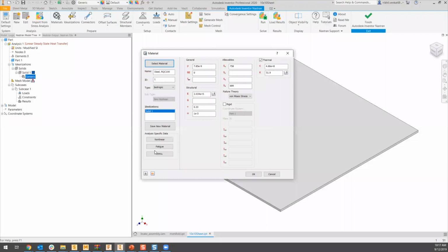Now, by the way, one of the things that I didn't mention previously is this is also how you would analyze heat transfer at areas that are going to be welded, right? So you're not actually going to be able to analyze the weld beads themselves, but you will be able to analyze, excuse me, the temperature profiles of the two materials being welded. So if you want to look at what that temperature profile looks like, you would need to do a nonlinear heat transfer.